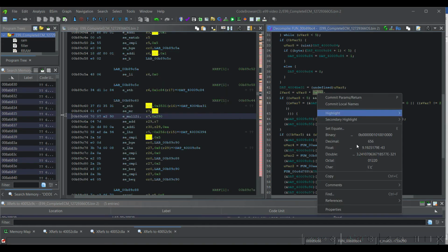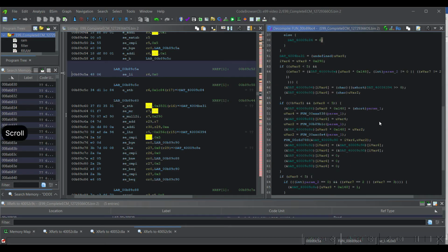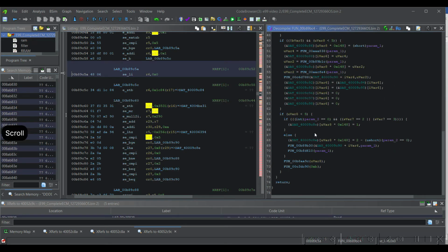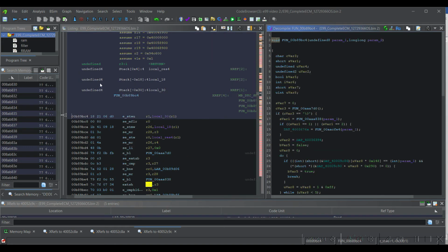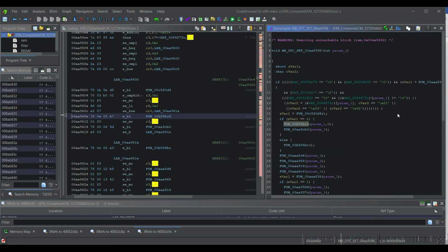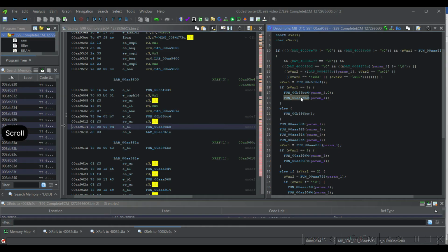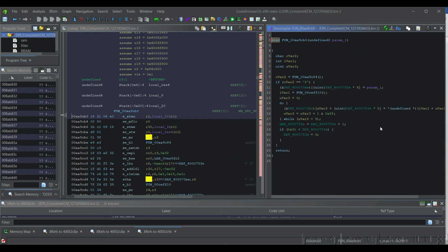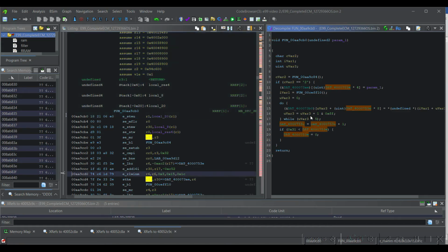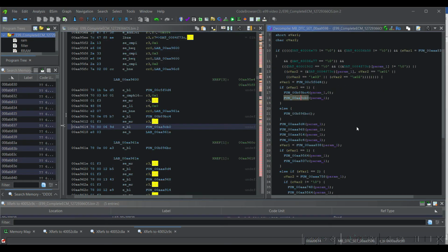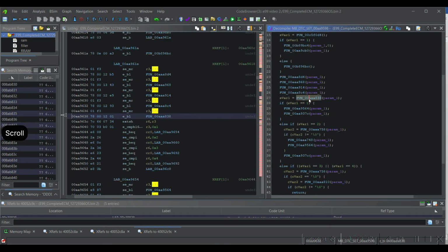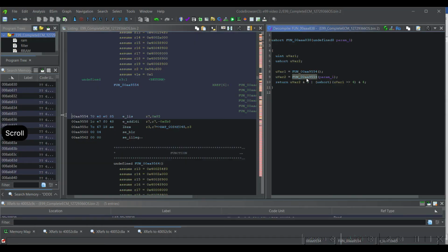0x290656. So what you're going to be looking for is a case in which you want to track this to your DTC hex table, and it might require you tracking a value being written to a RAM address and then read from a RAM address. And then you might be able to track your DTC hex table.